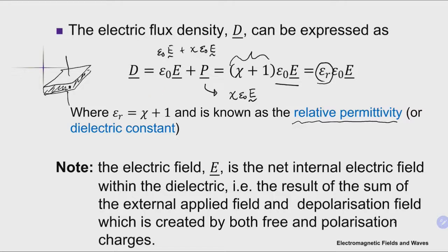So in air, epsilon r is equal to 1. Relative permittivity is comparing to air how well this material is polarized. So in air it is equal to 1, so basically in air it is just epsilon naught. Other than air, for an insulator, it will be something greater than 1. When you have, let's say, PTFE Teflon, then you have a different epsilon r.